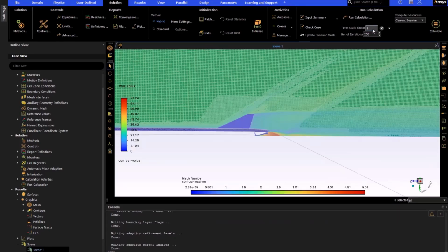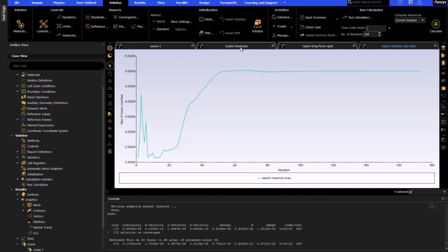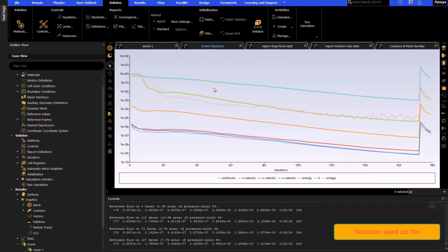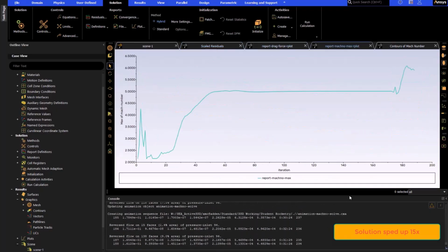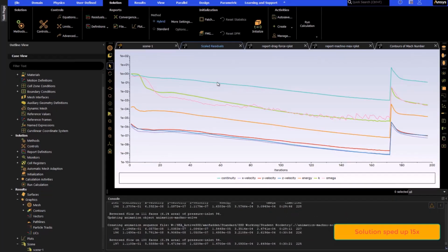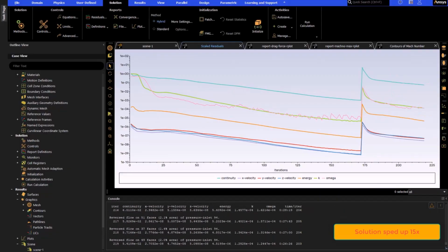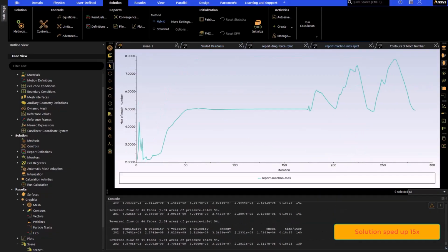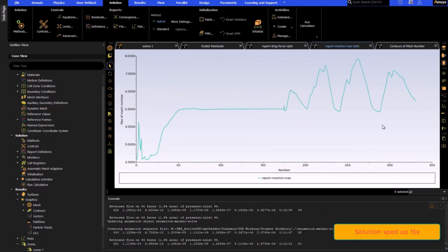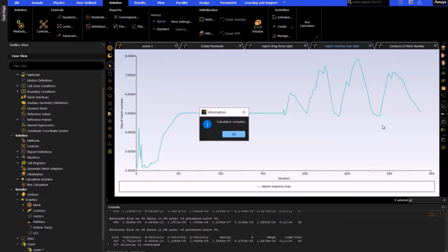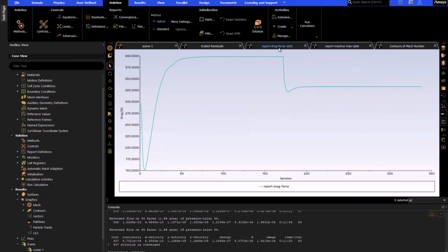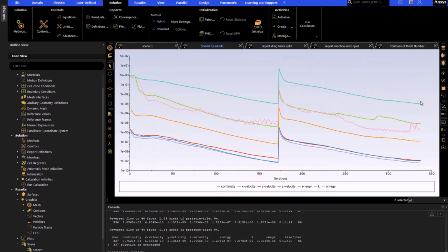Finally, we'll rerun the simulation to calculate the refined solution. The residuals and monitor values will change abruptly before slowly converging again. Note, this simulation was run on 32 processors due to the increased mesh size. As the solution progresses, we observe the change in monitor values and the reducing residuals. The calculation finishes as residuals have reached their specified limit, however the velocity monitor is not converged.